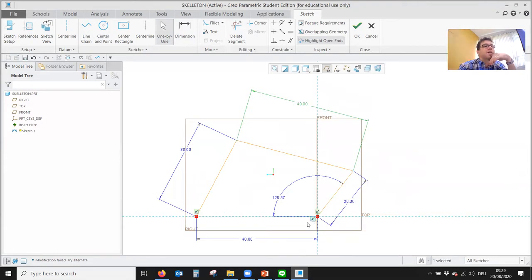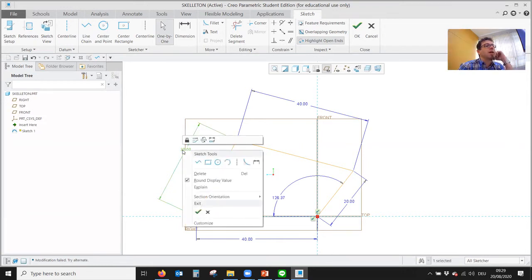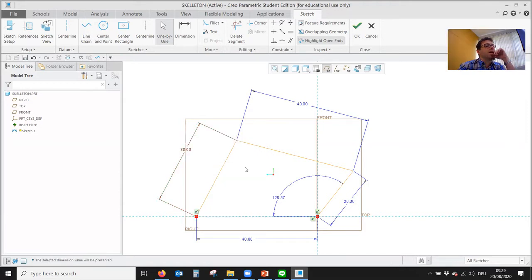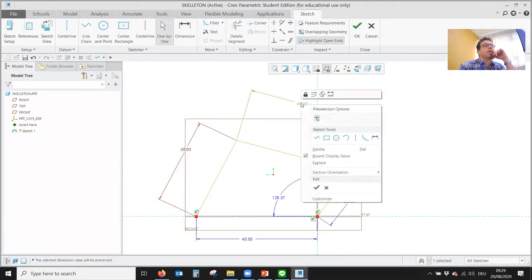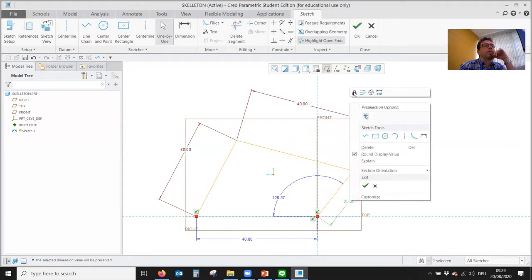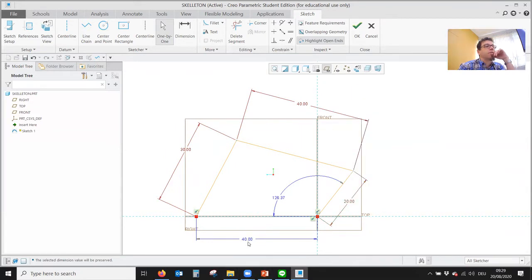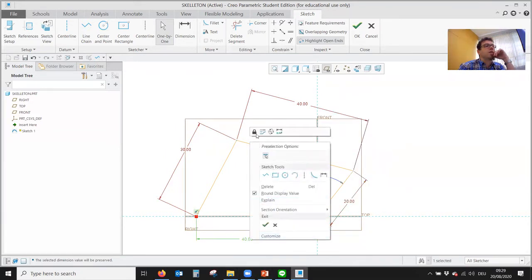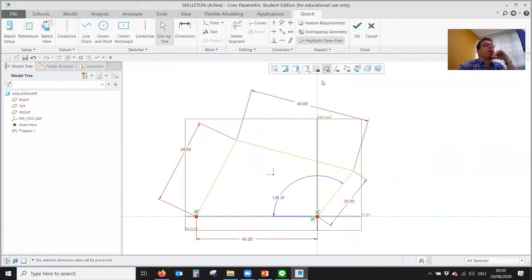So now, as I said, I want to lock the lengths of these lines, which will represent mechanism linkages. So if I change the sketch to show a different position, they will not change. And you'll see this little sign here that obviously is a lock. If I right-click the dimension, so mark first, right-click. This one too. So now I can change this and it will look like the mechanism is moving.